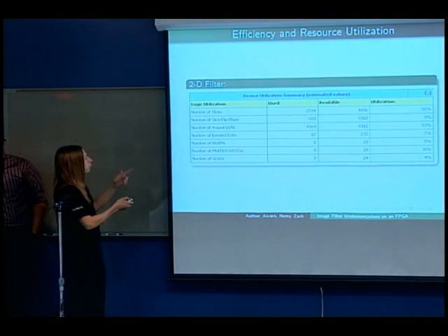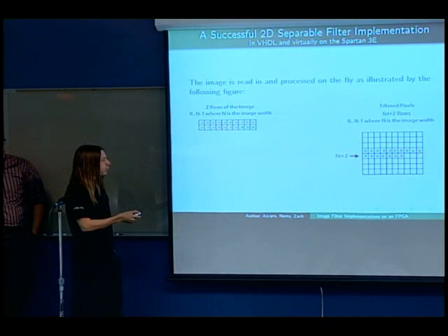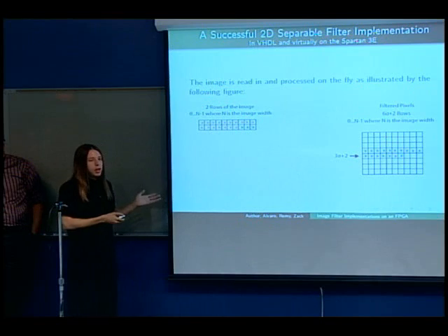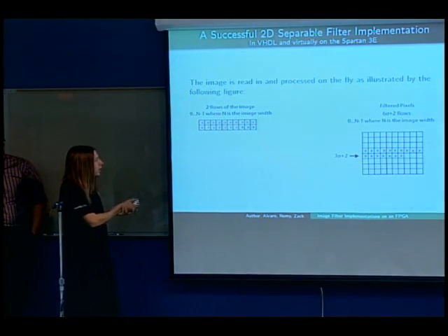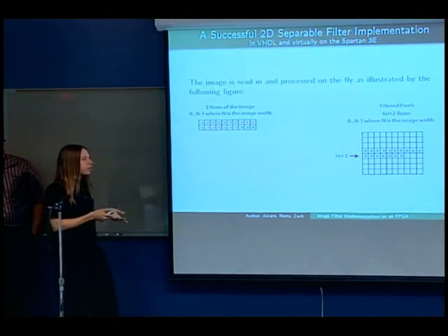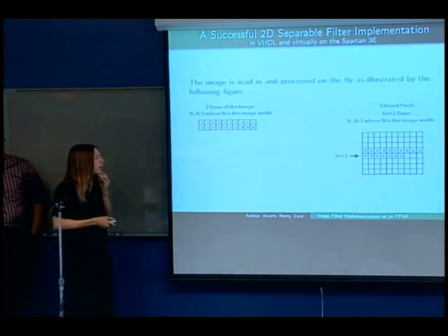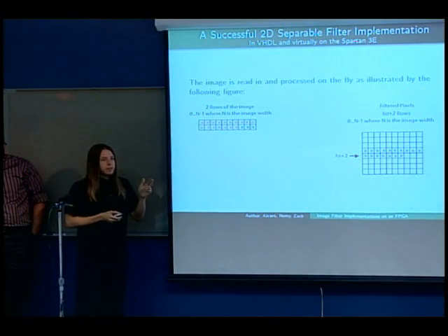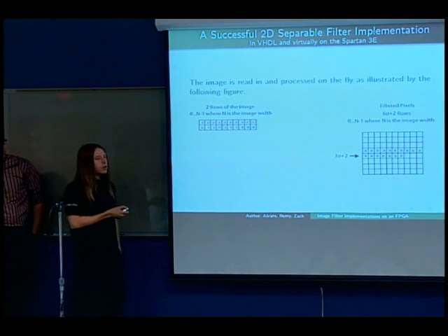But anyway, once this has enough values, which is when this is done, it actually begins to implement pipelining to take the values from this register here and start calculating them here. And by the pipelining architecture, we can actually do 2 convolutions per clock cycle, and that allows, in theory, one pixel in, 1 pixel out, almost instant real-time filtering of images.